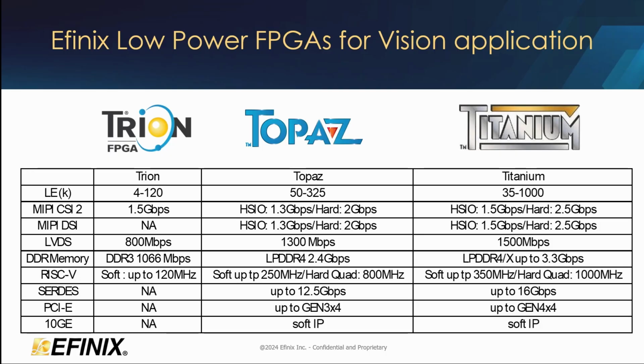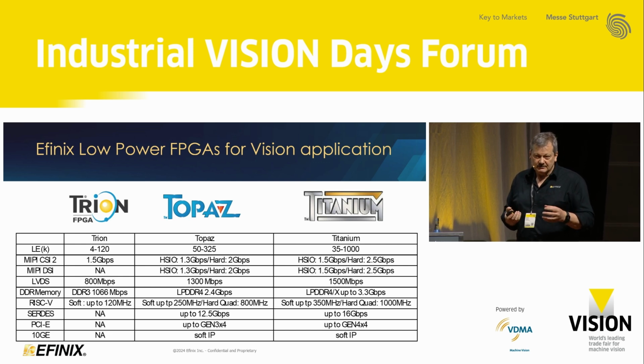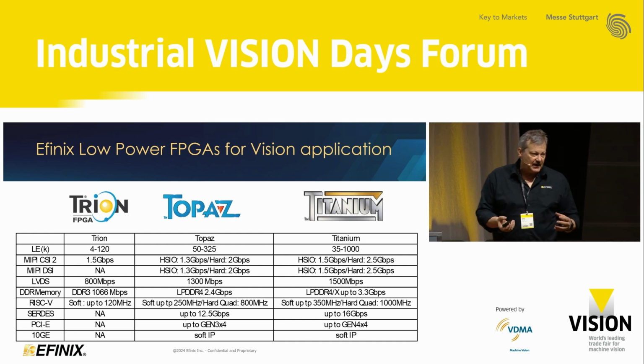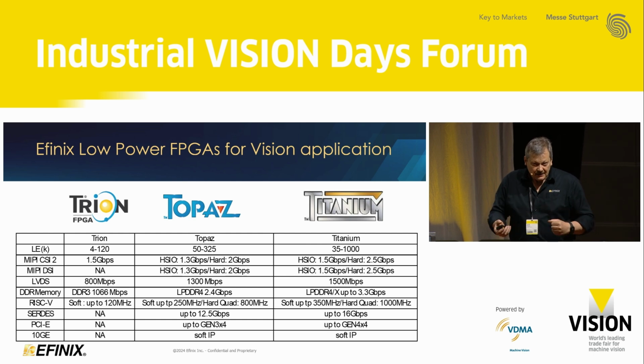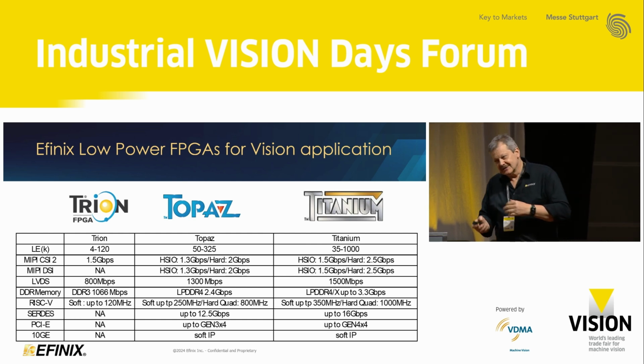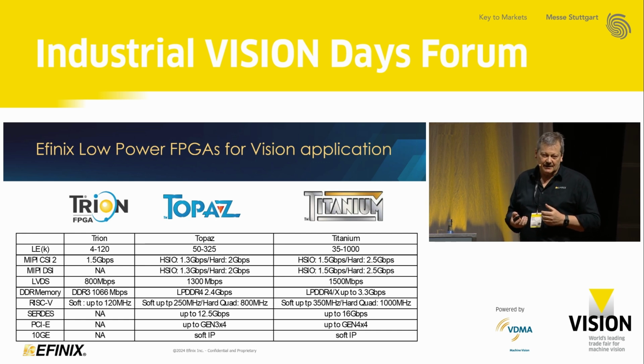But the big benefit for you is, we did some measurements. We ran a core with 4 cores at 1 gigahertz, and we consumed roughly 500 milliwatt. If you compare this to other applications, this is a big benefit. And power consumption, or the related heat you are generating in a camera, is not necessarily a friend of yours.